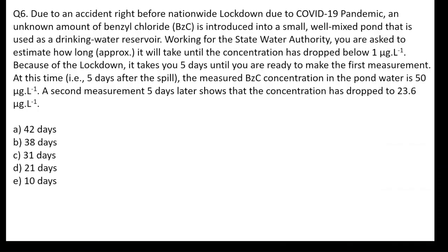So question number 6 is: due to an accident right before the nationwide lockdown due to the COVID-19 pandemic, an unknown amount of BZC, that is benzyl chloride, is introduced into a small well-mixed pond that is used as a drinking water reservoir. Working for the state water authority, you are asked to estimate how much time it is going to take until the concentration drops to 1 microgram per liter. Because of the lockdown, it takes you 5 days until you are ready to make the first measurement, 5 days after the spill.